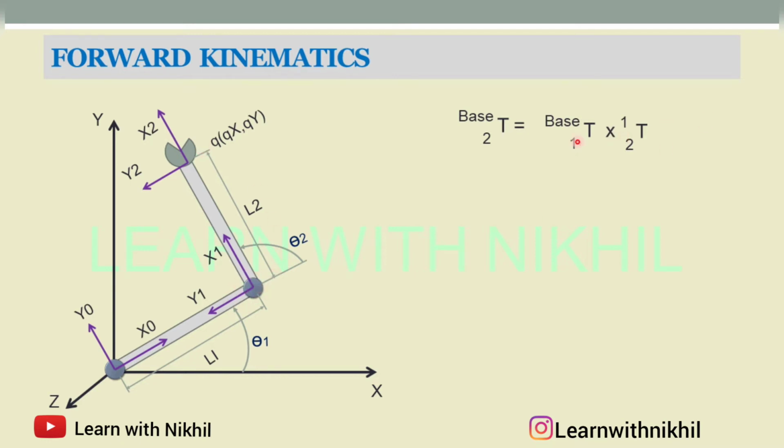So multiplying both of these will give me the transformation of the end effector with respect to the base, which we have to find out, and this is nothing but forward kinematics. So we will find these two separately and then multiply them.